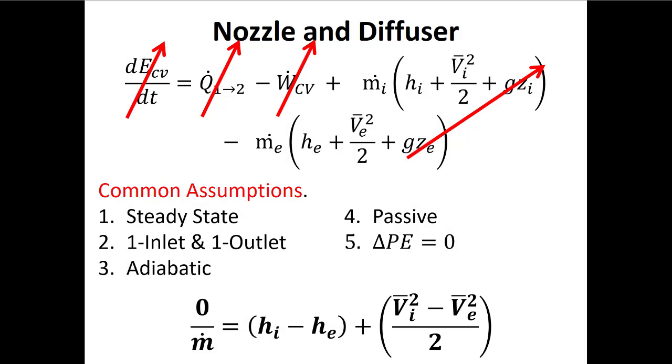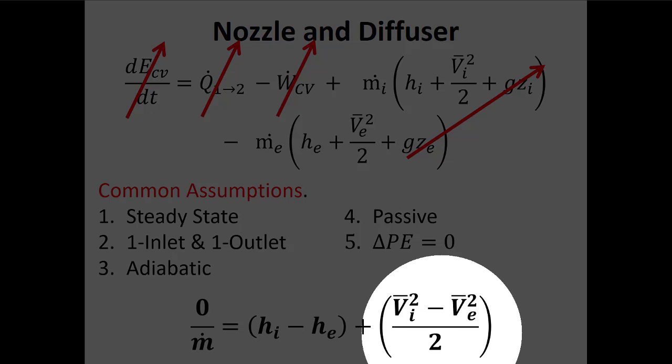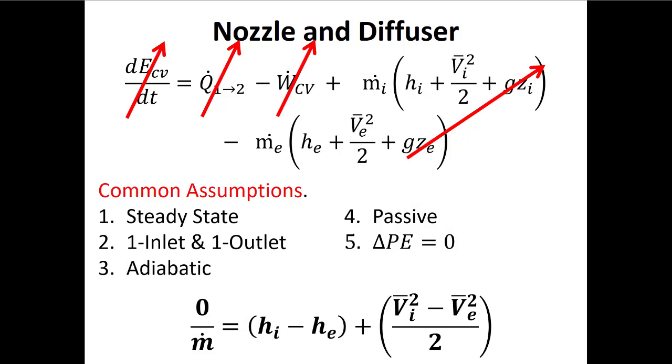Now, if I'm doing this, my spidey sense starts tingling because I've got this kinetic energy term. I know that the units here are going to be messed up, right? This is written as if it's in metric. If this is in imperial, then I would have to add that gc in the denominator as well.